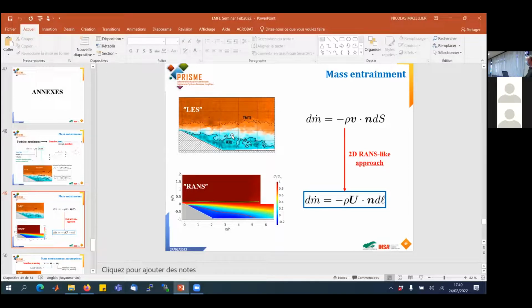So your PIV is a sort of experimental LES problem. At the end of the day, this is the real life problem. This is just a filtered view of the problem. So we cannot get every physical insight using only this, okay? But this one is tricky.